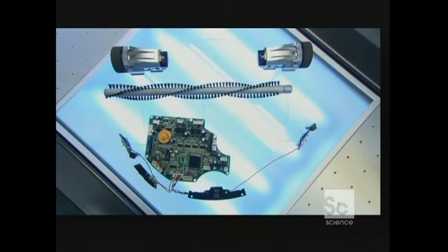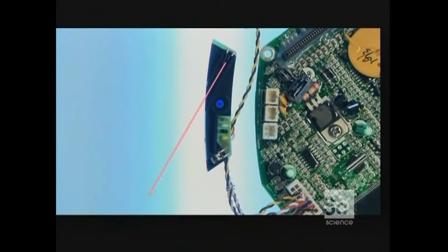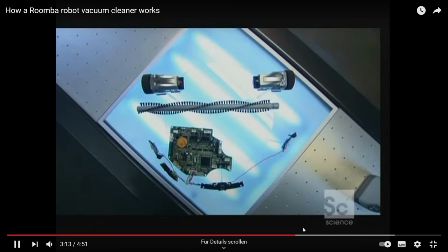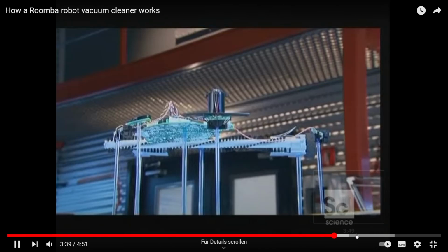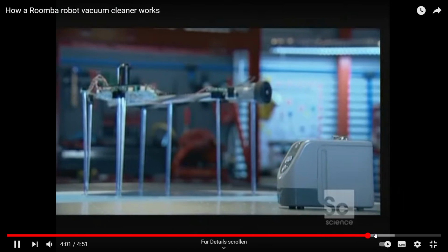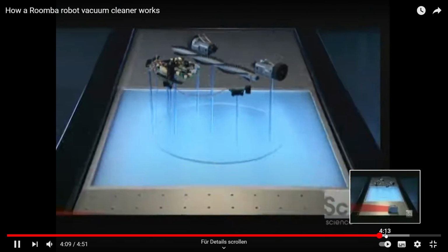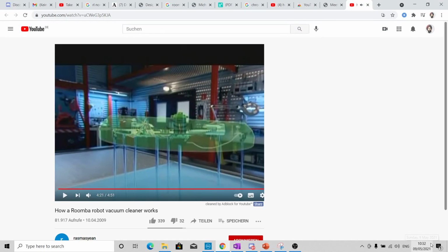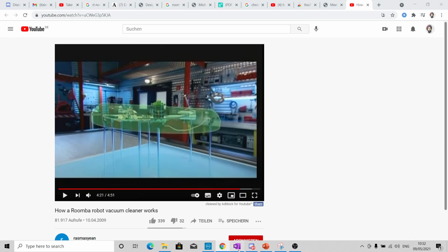The receiver detects the light after it reflects. The emitter is positioned so the infrared beams always hit the wall at a specific angle. When the robot is at the ideal distance from the wall, 2/10 of an inch, the infrared beams bounce directly back to the receiver. When the robot reaches this border, it knows what's off limits. Then, I think we got what we wanted from here.